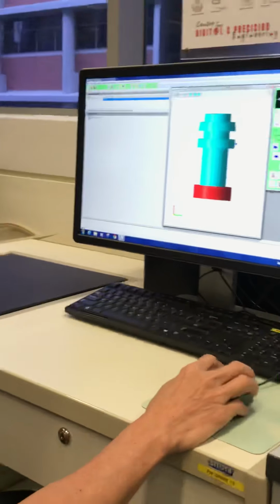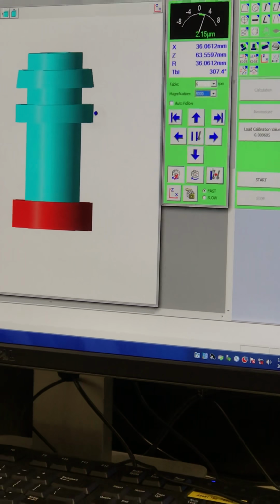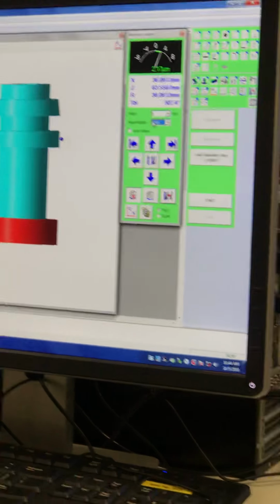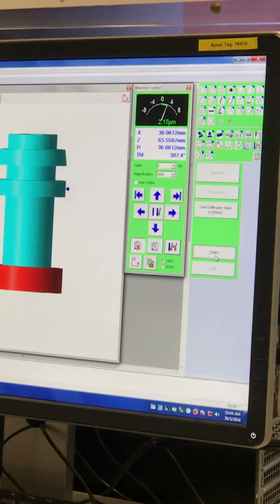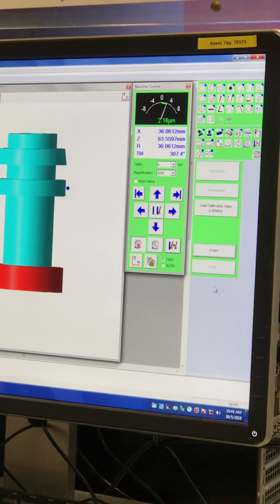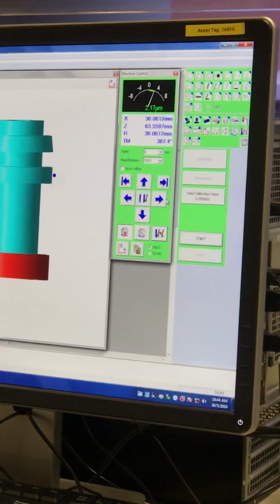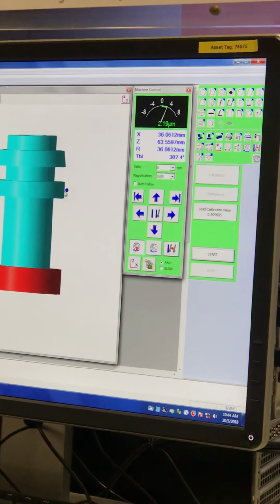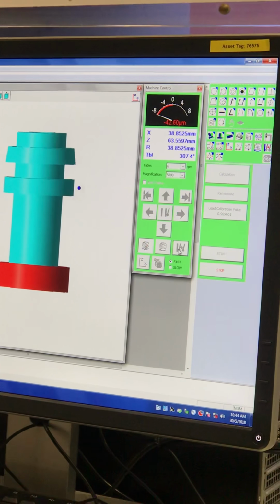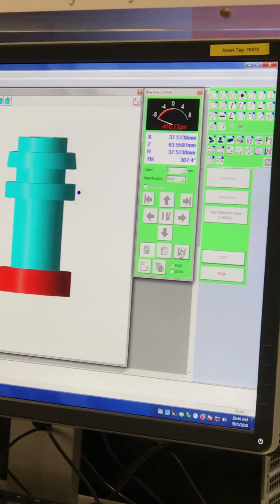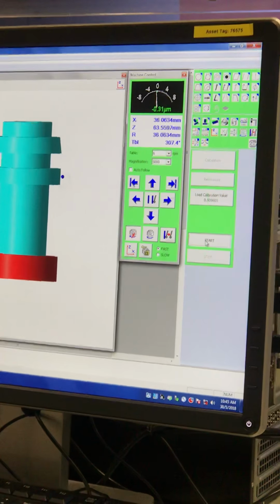You need to change the magnification to 5,000. Speed is 6. Okay, then start again. Click on the roundness icon. Move the stylus to the midplane. Already in the mid plane, right? Then click auto set. Auto set is here. Then click start. Start is here.